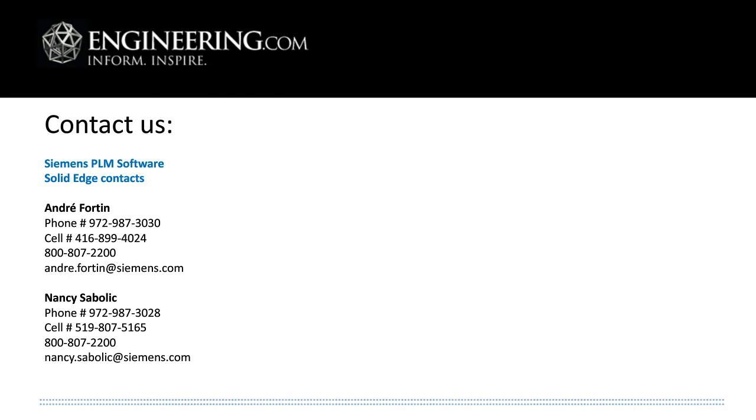Look for a certain minimum. I think Matt said it right. You don't want or need the top of the line. Maybe the second or third down is good enough. Always a lot of memory helps. Then I would look to simplification. Like I said in my presentation, you really need to analyze the kind of assemblies you're working with. If your assemblies have a lot of detail, such as thousands of bolts, and you do have the threads on them, well, there's an obvious screaming area that you can take a look at.